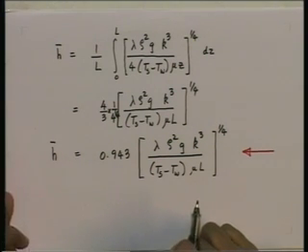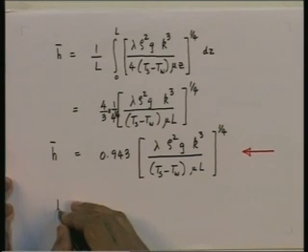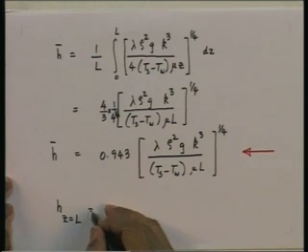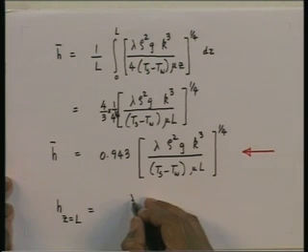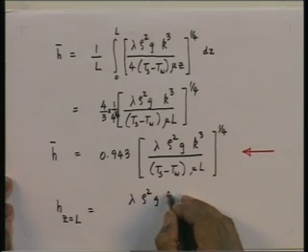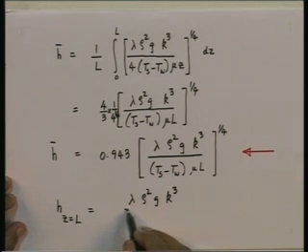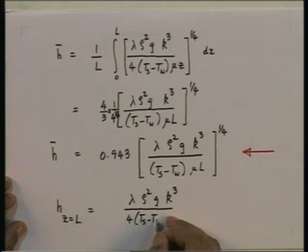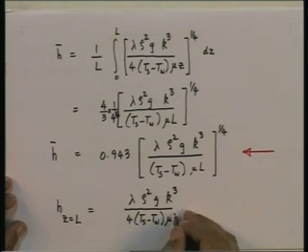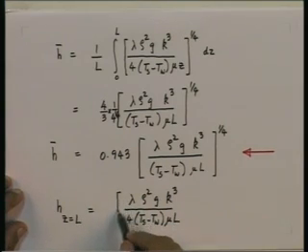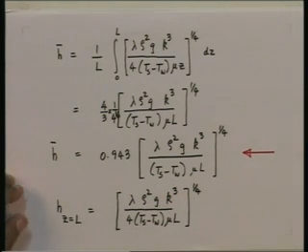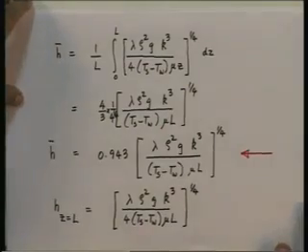Now, h, the local heat transfer coefficient at the bottom of the plate, if I ask you, if it is a plate of length L, h at z equal to L is nothing but lambda rho squared g k cubed divided by 4 T s minus T w mu L, the whole thing to the power of 1/4. That is our value of the local heat transfer coefficient at the bottom of the plate at z equal to L, if I take a plate of length L.